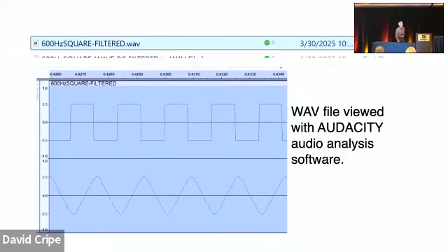Oh yeah, another thing, I have not done it, but I understand you can use a waveform as an input to your circuit too. So it sounds like you can take a receiver, maybe set it pretty broad, and you're listening to something pretty nasty and you make a recording of it, make that recording a wave file, and then put that wave file in your SPICE simulation, and you've designed some cool thing to filter that stuff out, and then you can look at how that came out. That sounds really interesting and useful.